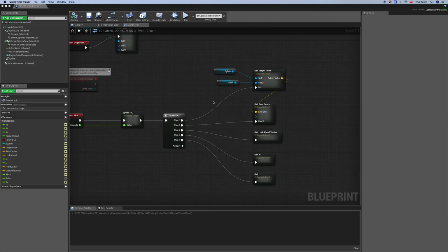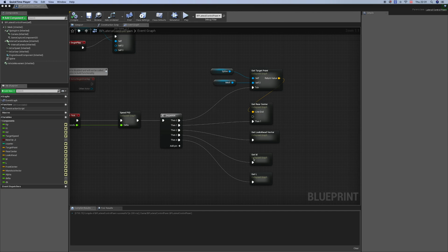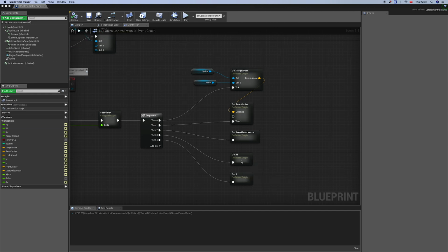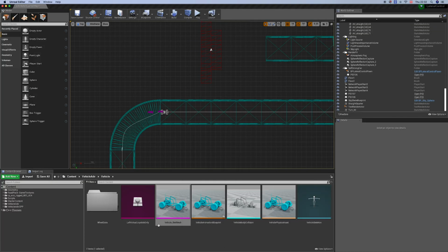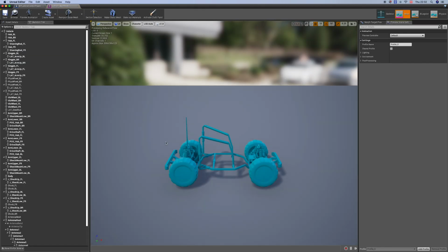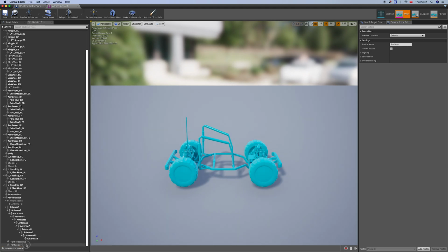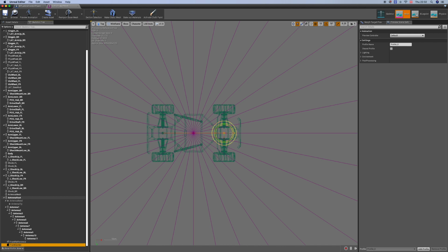So I lost part of the video, unfortunately, but I will repeat what I have done to get LD and L. The first thing we need to do is go to the skeletal mesh and add another point which represents the front center. It's the same way we created the front reference. We need it to get this L, which is the distance between rear and front.